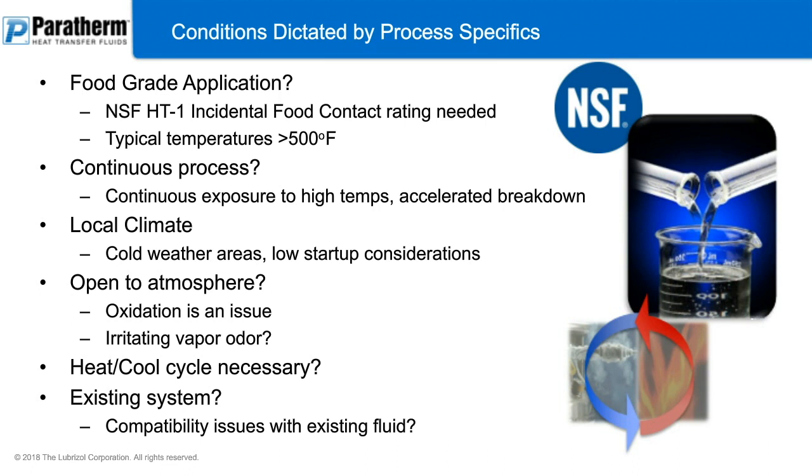Well, that makes your selection process quite simple at the very high level. If it's that kind of an application, you need to make sure you choose a fluid that has NSF HT1 incidental food contact rating.